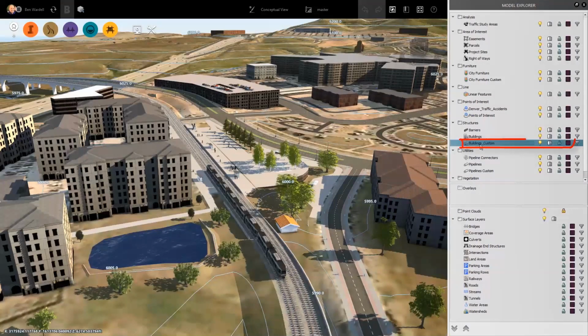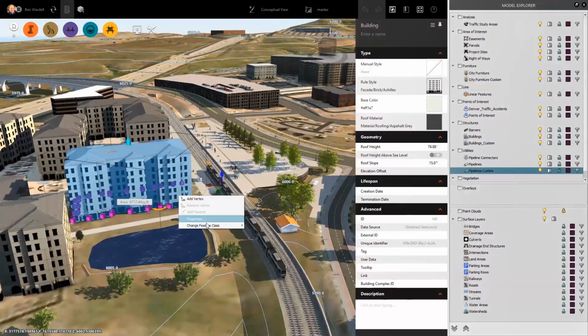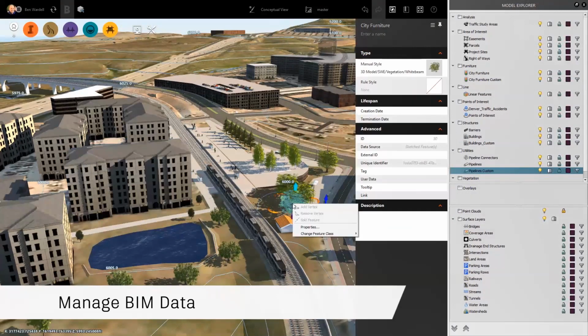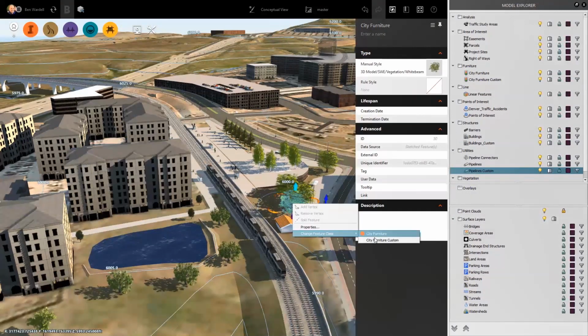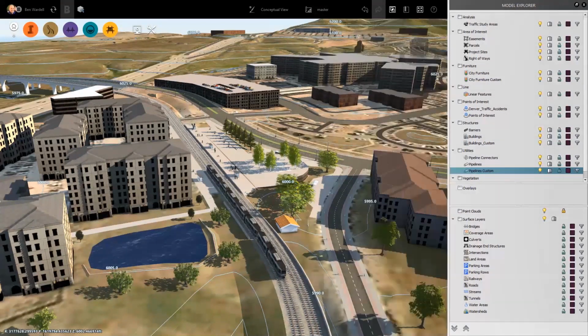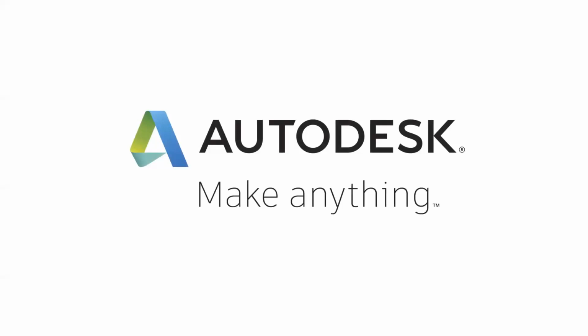So you can have buildings which are customized, or the same building that you got from Infraworks within the Infraworks interface itself, or it can also work with the GIS information that you have got from the ArcGIS platform, whether they're roads, parcels or land uses, or just buildings as you have seen. So you can now start changing the information that the particular model component has, so that you can save it back into the ArcGIS platform as well.